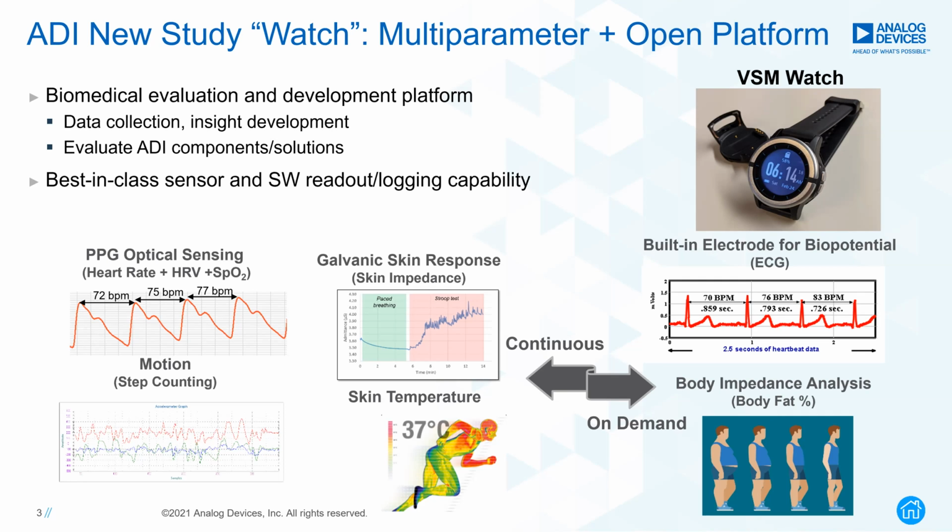We also have an impedance sensor. We call it the AD5940 based impedance front end, which monitors the skin impedance. And a temperature sensor, ADT7422 or 7420, which is a fairly accurate digital temperature sensor.